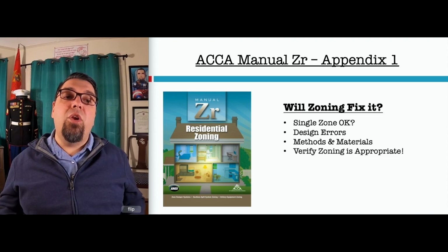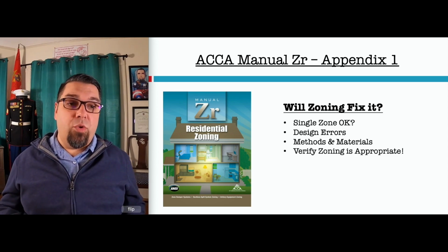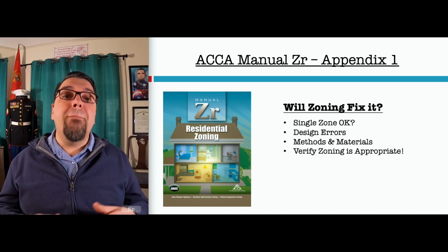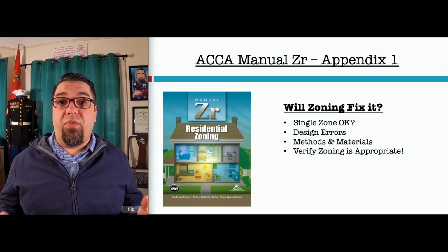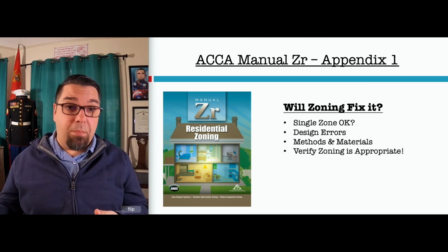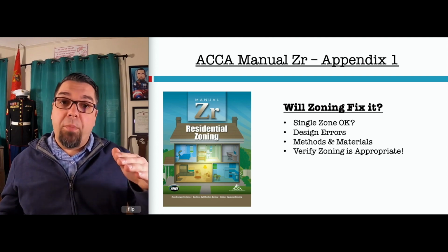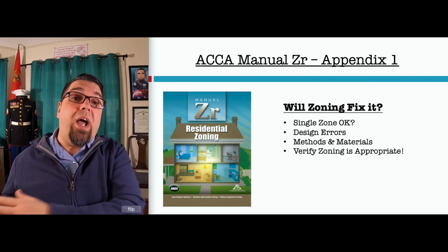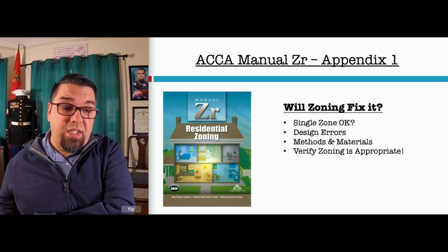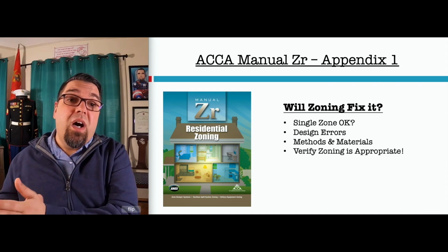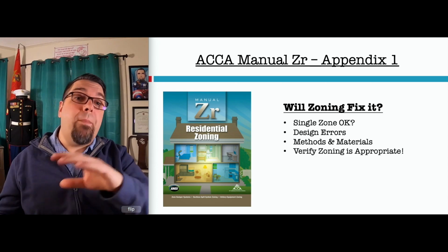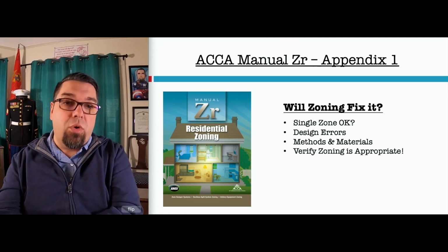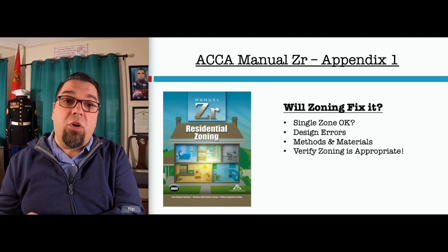Obviously, you got to know the right methods and materials in order to really zone the system right. There are many different ways of zoning a system. There's the basic bypass and dump zones. There's a lot of variable position dampers that don't require bypass systems. And in fact, there's some ductless manufacturers that make ducted systems that will not let you use a bypass duct. You have to use their zoning system for the system to operate correctly and efficiently.